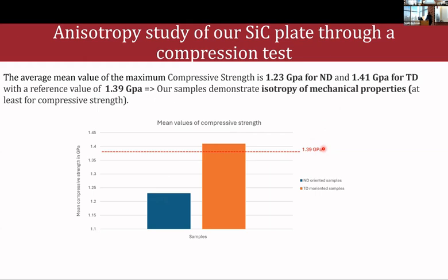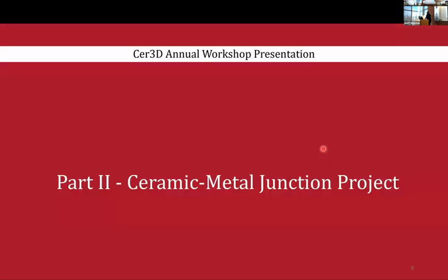So even though there is this huge gap, statistically, we were not able to assume that there is any anisotropy in the material, because when we conducted t-test statistics on our results, they are still confident, if we take into account that ceramics are full of defects and the samples were not flat also. So sometimes the samples were not only compressed, but some bending was also involved during the test.